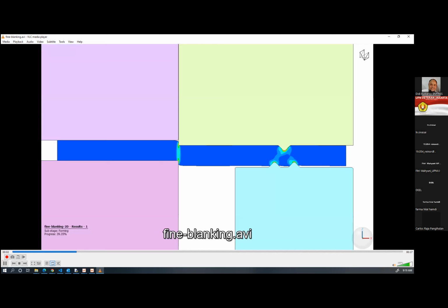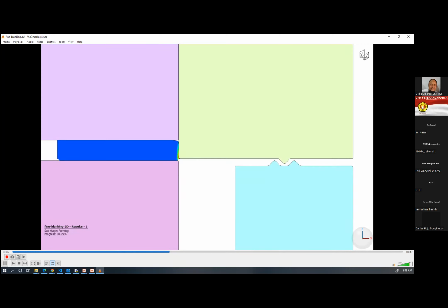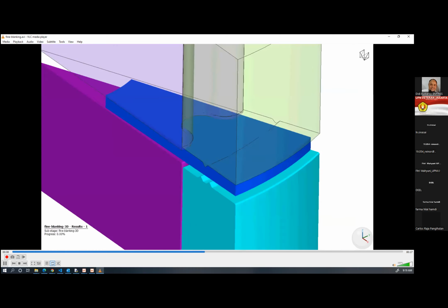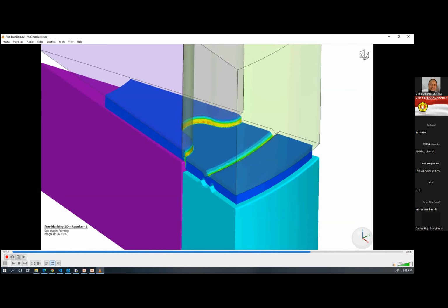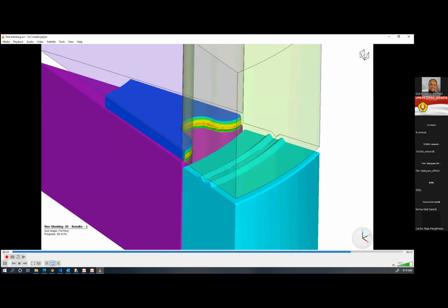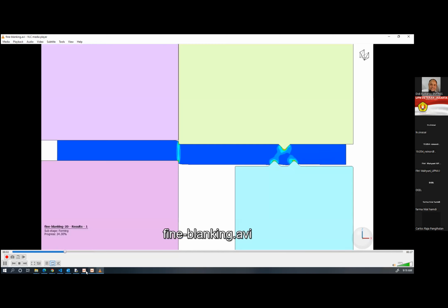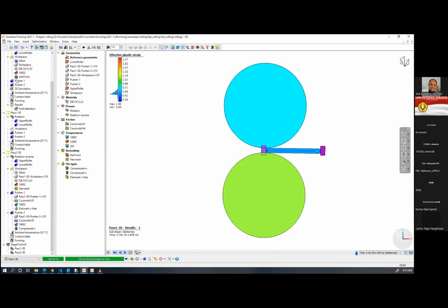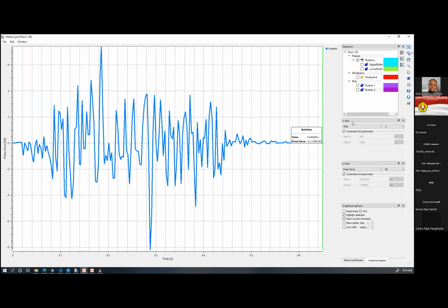Okay, any other queries? And can we know how much tonnage is needed for this process, right? Yes, we can note the tonnage that is needed for the process. And since the tonnage point came up, for a rolling operation, we can also find out the torque required for the machine or the motor to do that. So this is the axis press force. The press force is nothing but the reaction forces onto the rollers.